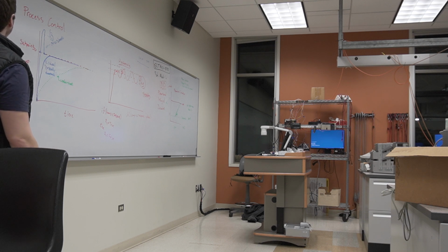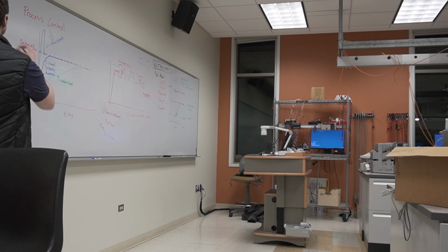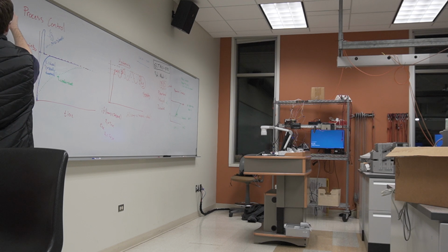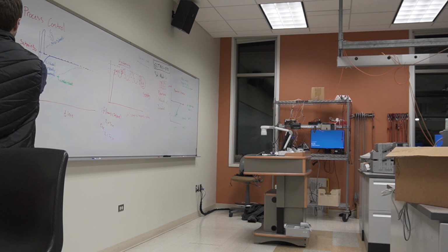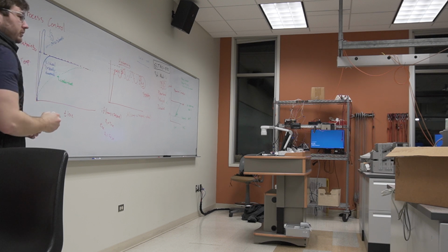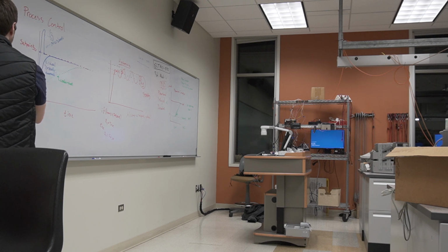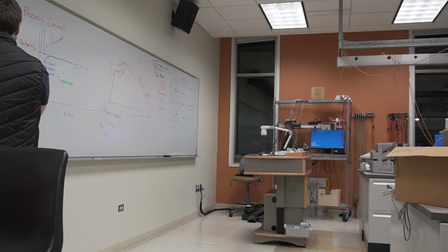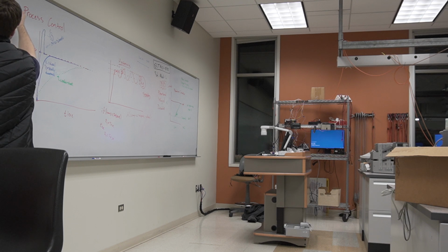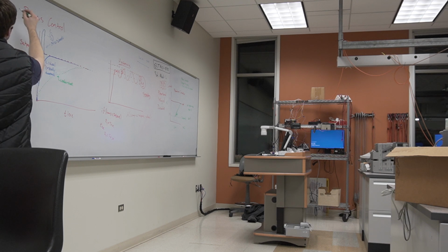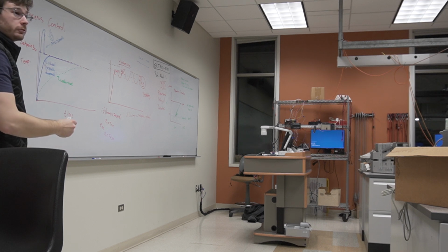Assume that the proportional value should be 1, but we don't know that. In our testing, we find that 0.98 works pretty good, right? For most cases, it gets us within shooting distance of where we want to be. But the issue with proportional controllers is that if they're off by a little bit, say the 0.02 here was really important, we'll always be off by 0.02.